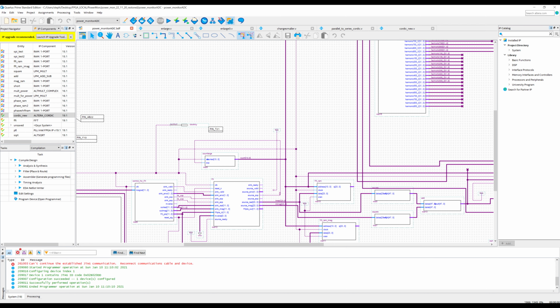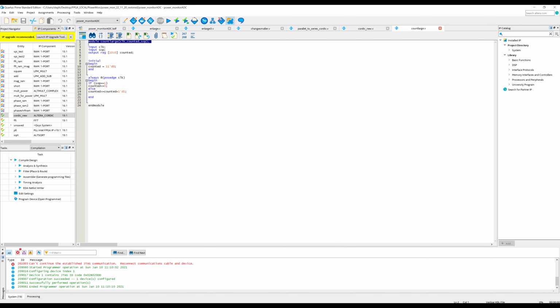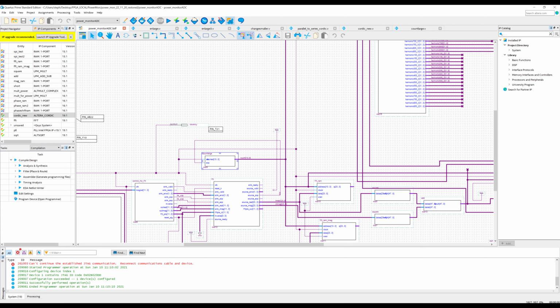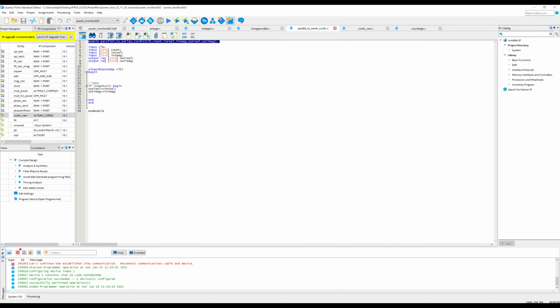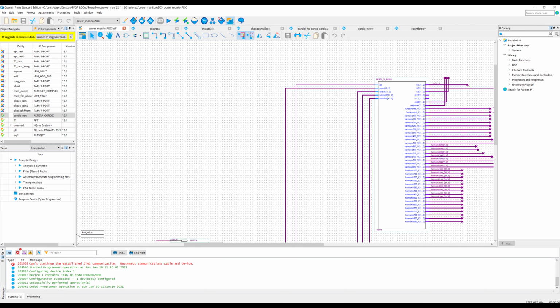So having a counter here, and it might be worth clicking into this. So this counter will reset itself when start of packet is equal to 1. So we know that the value of this count will correspond to the frequency bin that we're currently on. And the count is output from this module, and it goes into this big module here. Now let's have a look what's going on inside. So all we're doing at the moment with this parallel to series module, I'm actually suspicious of this.